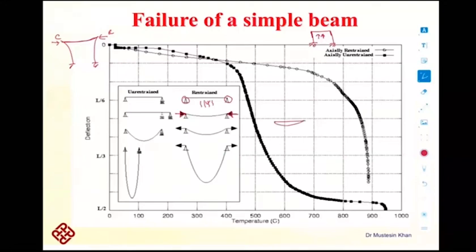would deflect too much and the properties would be so less that it will not take load in a flexure action or in the bending action. Bending action means it has both compression and tension. The material properties has reduced so much, now it will act just as hanging as a cable. At this stage you could consider that the beam is just hanging and the load is just lying over it.